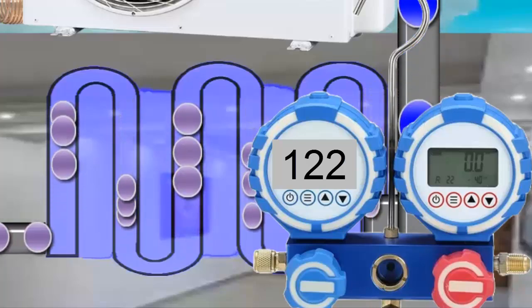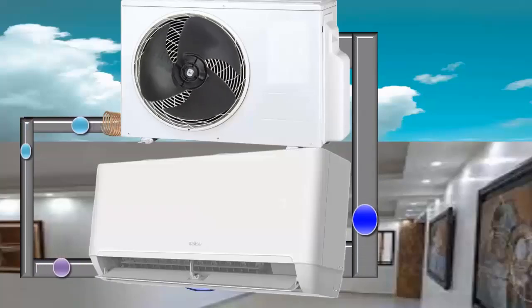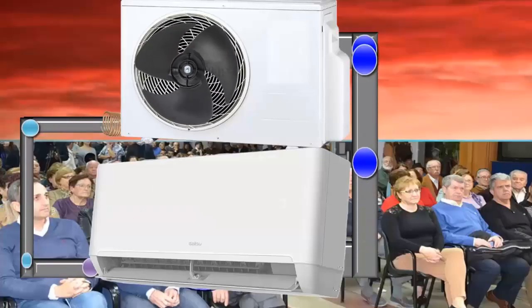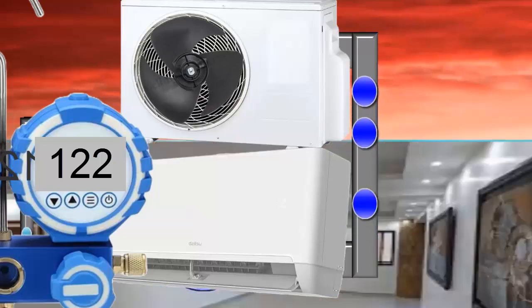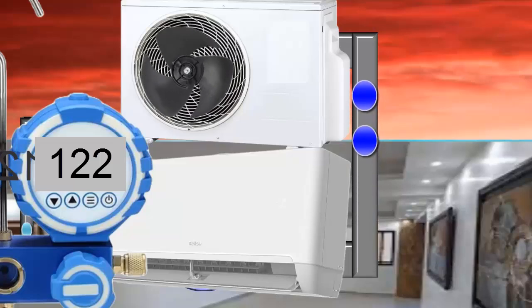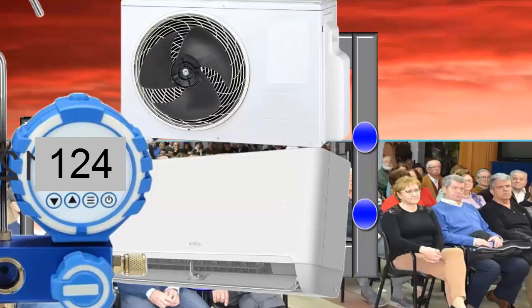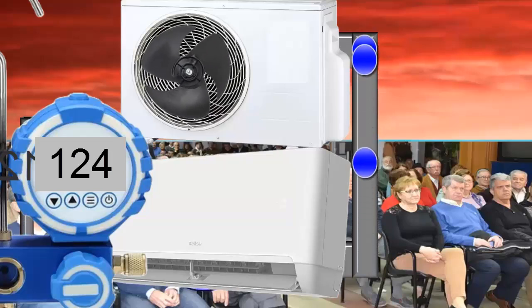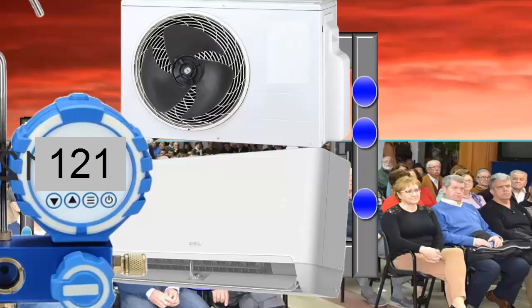Low pressure is not constant and varies, although very slightly, depending on the equipment's operating conditions. For example, on a sunny day with many people in the premises, the R410A pressure will increase slightly but always stay close to the original value. On the other hand, on cooler days or with fewer people, the R410A pressure may decrease.